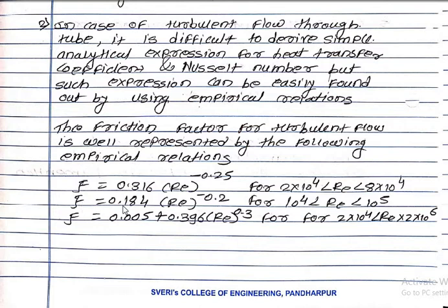Then friction factor is equal to 0.184 multiplied by Reynolds number raised to minus 0.2 for Reynolds numbers between 10 raised to 4 and 10 raised to 5.